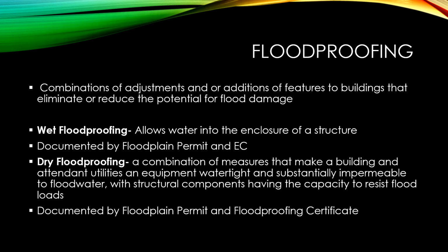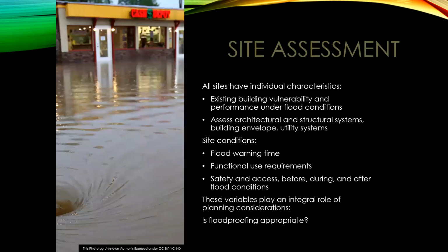And so we need a floodplain permit, like everything in the floodplain needs, and then a floodproofing certificate. So if we have an existing building, or for a new building, we have to assess the site. We have to look at the flooding characteristics and what kind of structural integrity we need for this to work, because we have to know how it's going to perform under expected flood conditions, as well as being able to